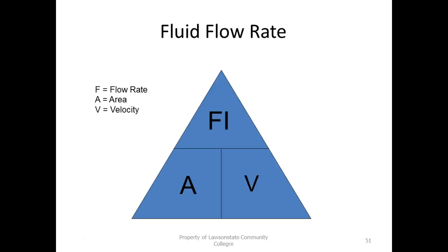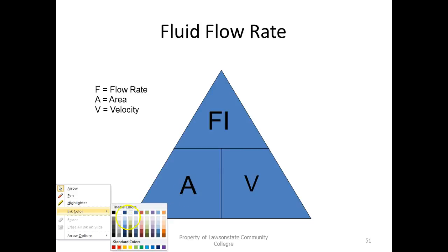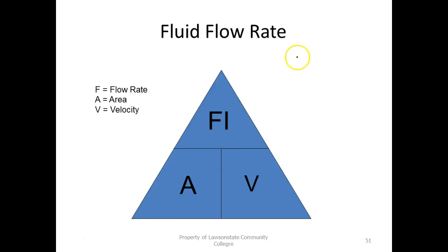So electricity, our main law in electricity is called Ohm's law. People make this mistake all the time. So I come over here and I say, okay, what's Ohm's law say? It says the voltage is equal to the amount of current flow times the amount of resistance in the circuit. And what variation of that formula you use depends on which two things you know about, right? So somebody called out a formula for area, but they said force over pressure. But the problem is that we didn't know two things.